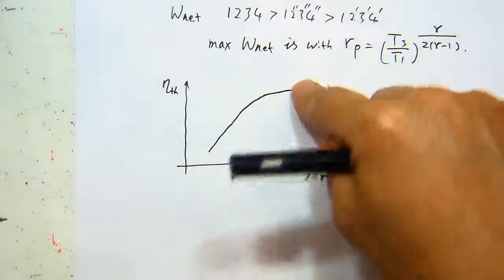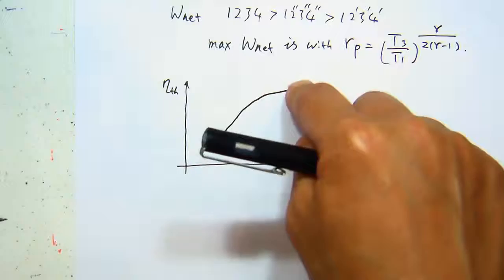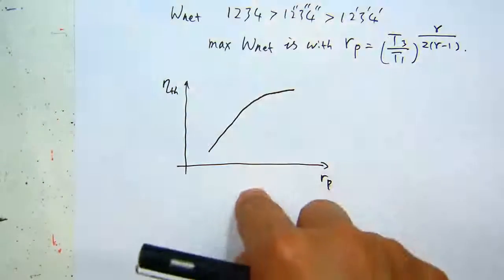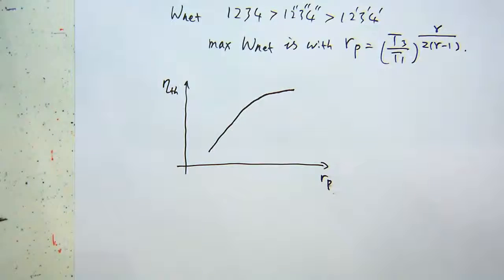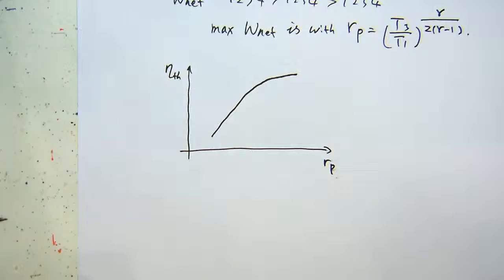So at a very high pressure ratio, you actually do not gain as much as you did at a lower pressure ratio. And the high pressure system is actually quite expensive. For industry, high pressure means more expensive because everything has to be built to handle that pressure. That's not necessarily justified by the high cost in the first place.